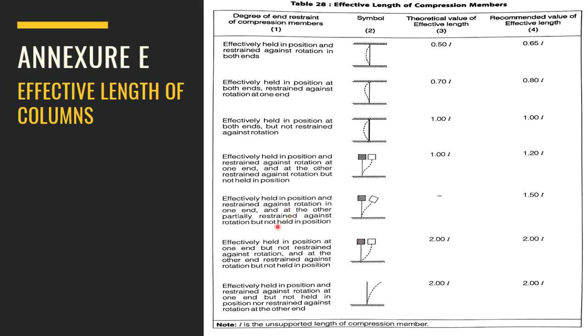So this is all about the annexures part, and the last annexure gives the design for T sections, moment of resistance, annexure G. It is a much easier one, very similar to rectangular section moment of resistance. For example, Mu limit is nothing but 0.87 fy Ast d into 1 minus 0.416 xu by d, like this. A T beam has to be designed on the basis of xu values, depending on where it is located, whether in the flange portion itself or in the web portion. Based on those, we have to design T sections as per annexure G.